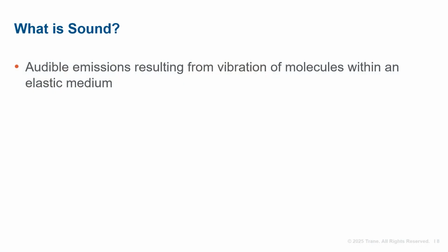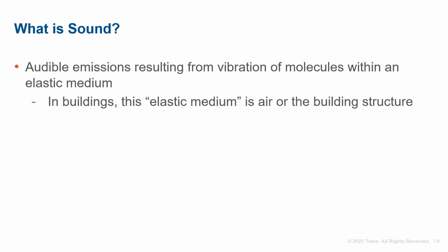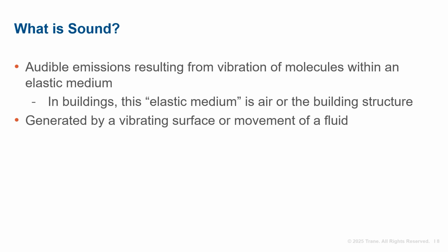I'm going to spend just a few minutes on the fundamentals of sound so that we're all on the same page with terminology. Sound is the audible emissions that result from vibration of molecules within an elastic medium. Now, in the context of an HVAC system or a building, this elastic medium is either air or the building structure itself. It's generated by either a vibrating surface or the movement of a fluid.